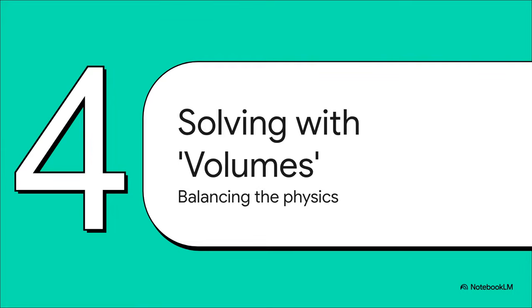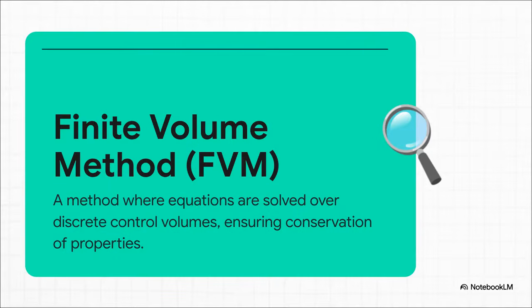Okay, so let's dig a little deeper. How does the computer actually do the math inside each of those little digital cells? Well, the most common way to do it is called the finite volume method. And what's so cool about this is it really taps into the physical intuition of what's happening.